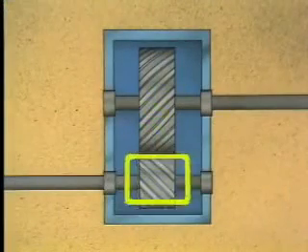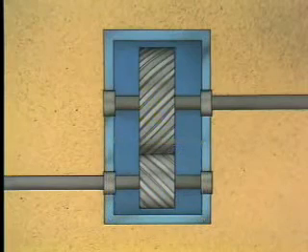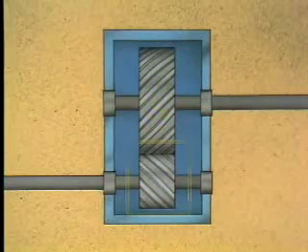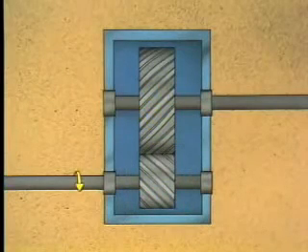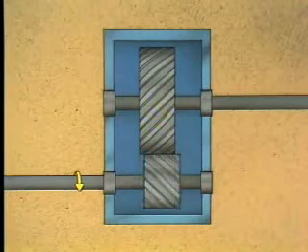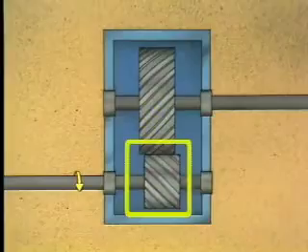We can use this illustration of a gear and shaft in a casing to see how end play occurs. When the gear is stopped, it is positioned as shown in the casing. As the gear is started and load is increased on the gearbox, the gear and shaft may begin to move axially. This difference in positions is the amount of end play.